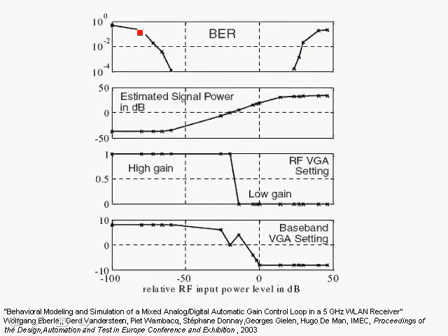This is typically referred to as the bathtub curve and shows the AGC in action, where we achieve a wide dynamic range using, of course, a fixed number of bits in the A to D.